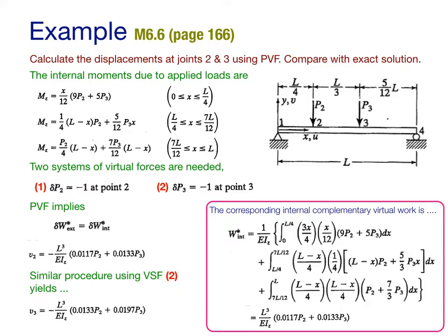As you can see, these deflections would have been really difficult to compute by other approaches. For example, if you wanted to just express the fourth order ordinary differential equation for the simply supported beam and impose continuity conditions, or perhaps even use the delta functions to represent the concentrated loads, you'd have to do a lot of algebra to compute the deflections that are sought here. And the principle of virtual forces just provided us with means to compute them really quickly and easily.